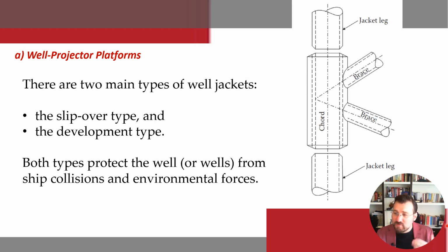So on the contrary, the development jacket may accommodate several wells, and this is installed prior to drilling. So this is used in conjunction with mobile drilling units like jackup or semi-submersible. All right. So that after the mobile unit leaves the site, the well conductors or production risers are protected by the four-leg jacket, for example. So while drilling, the slots in the drilling vessel or the cantilevered portion of the jackup is positioned above the top open portion of the truncated pyramidal structure of the jacket. Okay?